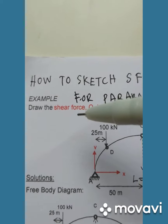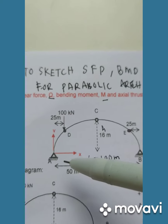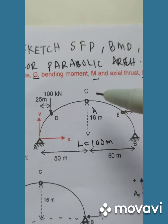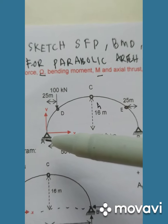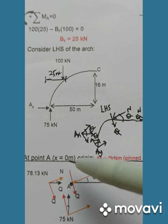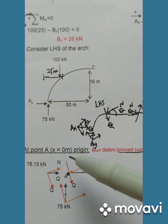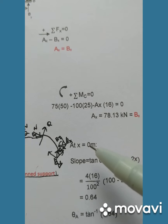Okay, continue. Since the question needs you to find the whole diagram, we have to find Q, M and N for each point: A, D, C, E and B. So we start with A. Since A is at X equal to 0 meter, A located at the origin, A also has a slope angle.